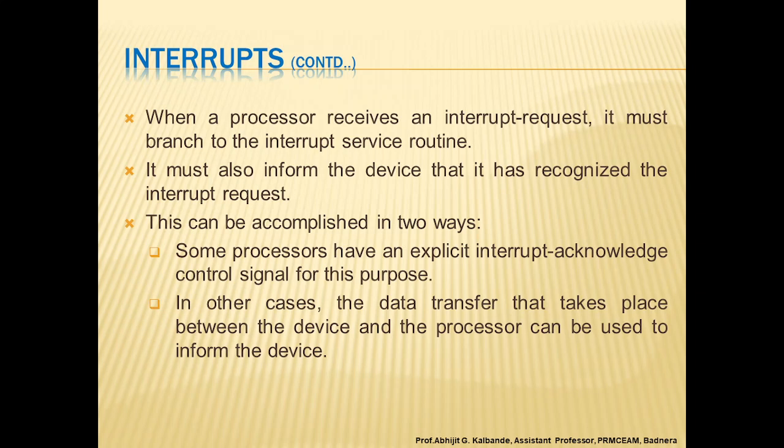As part of handling an interrupt, the processor must inform the device that its request has been recognized so that it can remove the interrupt request signal, typically with a special control signal on the bus. A common alternative is to have the transfer of data between the processor and the I/O device interface accomplish the same purpose. The execution of an instruction in the interrupt service routine that accesses the status or the data register in the device interface implies to the device that its interrupt request has been recognized.